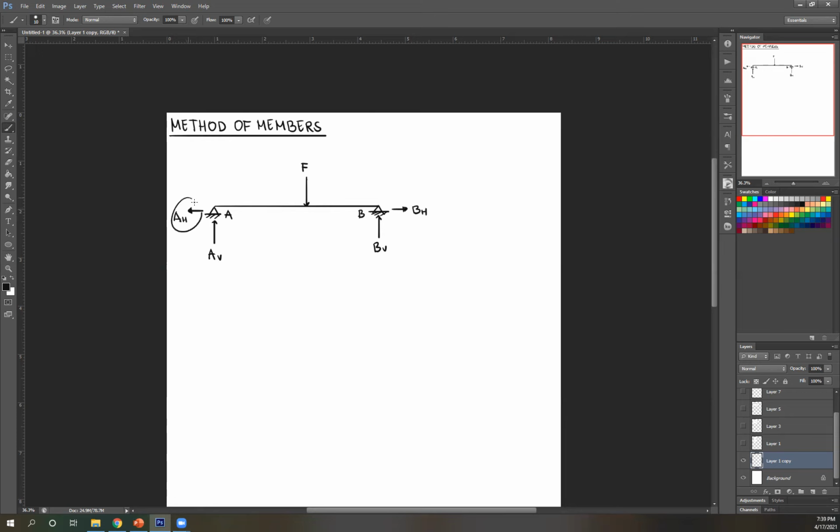Okay. Now, these two forces can actually be redrawn into a single force, its resultant. Okay. So this is upwards to the left. So the resultant should also be upwards to the left. And this is your total reaction at A. And then it's going to be at a certain angle. Okay. So same thing here. Our drawing here is upwards to the right. So your resultant is upwards to the right. So that's your total reaction at B. And once again, it's at an angle.